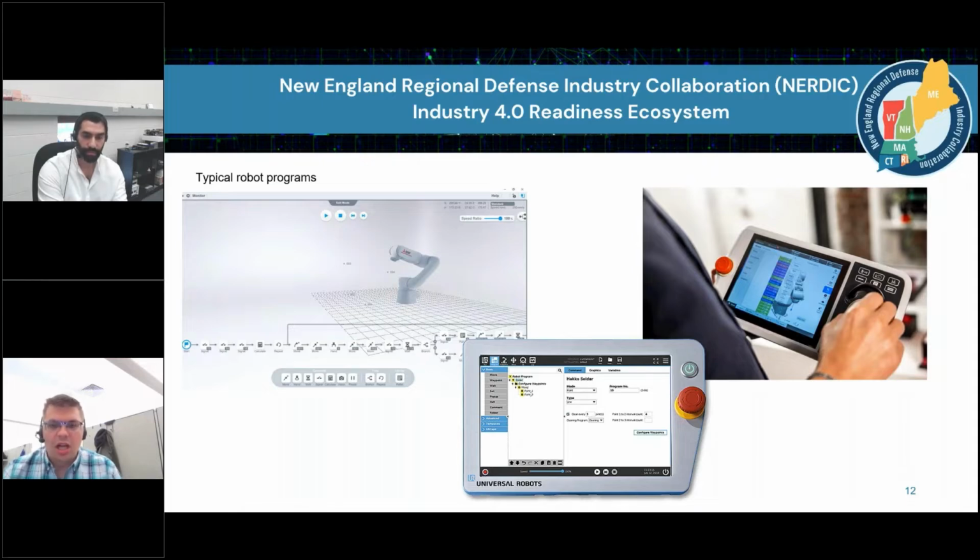And then finally, up in the top right, is ABB's version of their graphical interface that they use for programming their cobots. Again, it's very much flowchart based, fairly visual, doesn't have a lot of complex code structures. The advantage to both Mitsubishi and ABB, and to some extent UR, is that behind this screen that you see with the graphical programming interface is a fully complex standard program written in essentially computer code.